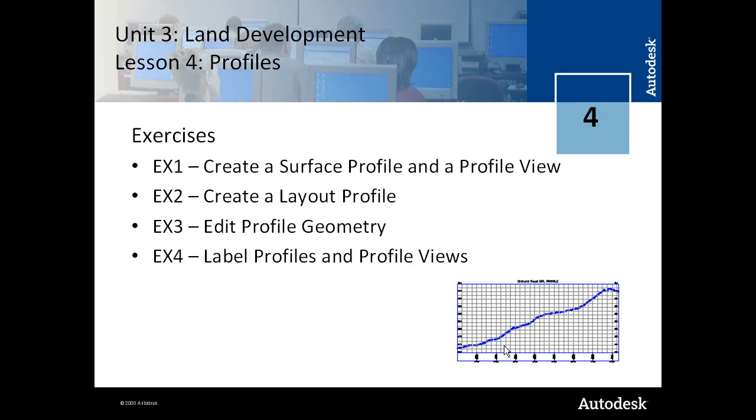Lesson 4 in Unit 3 addresses profile functionality in AutoCAD Civil 3D 2010. In Exercise 1, you learn how to create the surface profile and the profile view. The surface profile is the lay of the land underneath the alignment. The profile view is the grid object that shows the surface or the profile data.